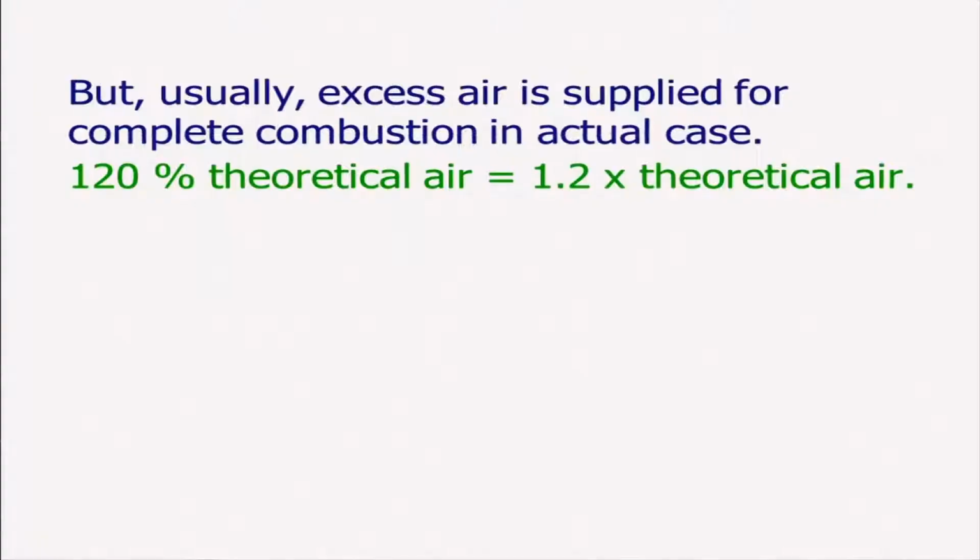Otherwise, what will happen? It will cause pollution, because some carbon monoxide and some other unburnt hydrocarbon will remain, and also it will be inefficient. It means the entire energy won't be released during these chemical reactions or burning of fuel. So, if I consider 120% of theoretical air, basically it is 1.2 times the theoretical air that we will have to give.